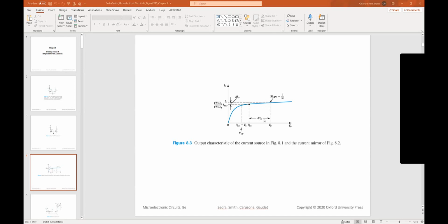Essentially, what is a constant current source? The voltage changes at the node, but the current doesn't. So you start getting that at this point over here. But it's not ideal, you would want a slope of 0, a flat, horizontal curve. That would be an ideal current source.